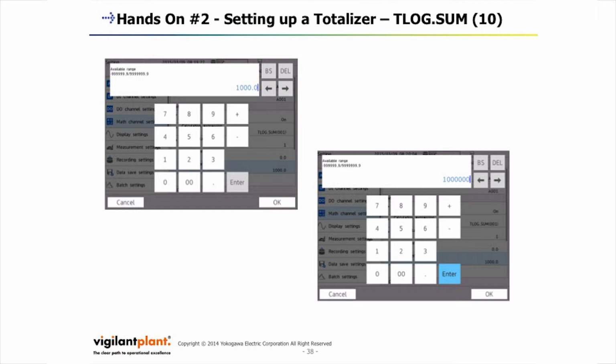Again, remember from earlier, we could set this to 99,999,999 based on the decimal place. We've got 1 decimal place right here, so we could actually go up to 9,999,999. If by chance this number of 1 million would be reached too quickly, you can add a slash K02 at the end of that statement, or K01, whichever constant you want to use, and set that to 1,000.